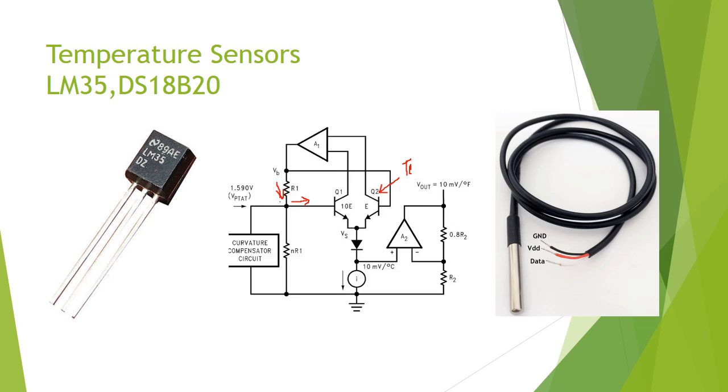The 10 times difference means the amount of current flowing will differ in these two transistors depending on the temperature. That makes the voltage different, and that voltage can be measured. Once the temperature varies, there will be a voltage difference that can be measured.